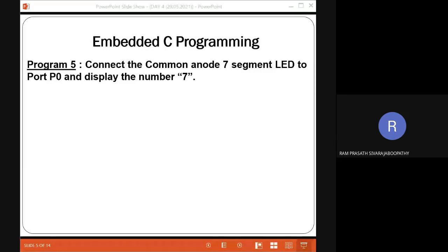Okay, fine. What are the things we have to do? We must use an entire port to connect this particular 7-segment display. So what naming can we give for this? Naming never starts with a number. It should not start with a number. If you write 7-seg, it is a wrong declaration. You must not use that, definitely. Okay? So what naming can we put? Kindly suggest. We have to give a name to that port. Yes, SSD, 7-segment display. Thank you.